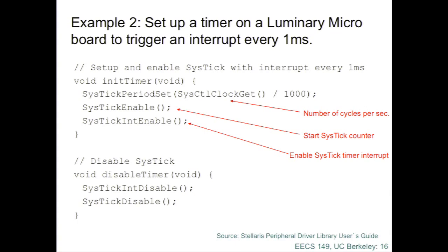And it makes a record of the location that was interrupted in the same table to come back to later, okay? So you can play with the return from interrupt and not return to the same place you were interrupted from. And that's how multitasking gets done in a multitasking operating system.